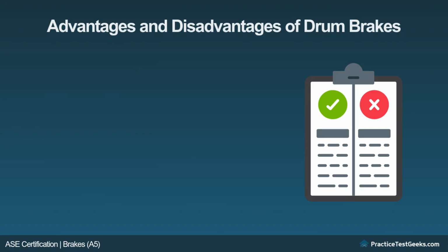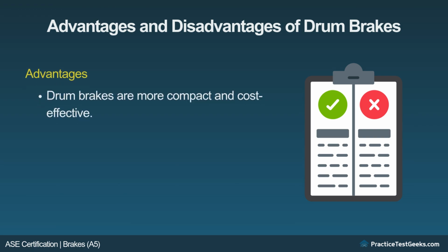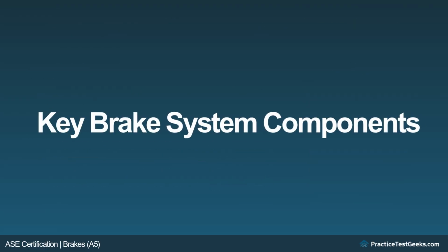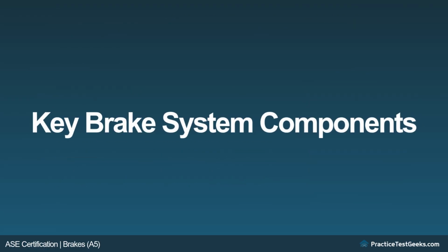Advantages and disadvantages of drum brakes. Advantages. Drum brakes are more compact and cost-effective. Disadvantages. They tend to overheat more quickly, leading to reduced braking efficiency, and they are less effective than disc brakes at dissipating heat. Key brake system components.